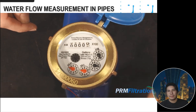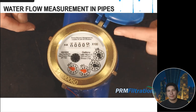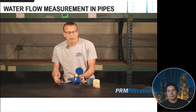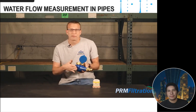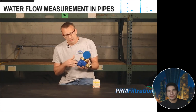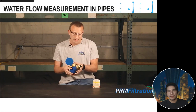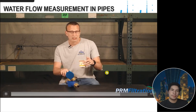As this continues to go, each of these will spin, and it will eventually churn this counter. This is a relatively simple design. It has an arrow on the side, which is pointing in the direction of water flow. So you want to make sure that when this is installed, the water is flowing in the direction of the arrow. Otherwise, it's going to read incorrectly. It is screwed in, with this ring holding it in.